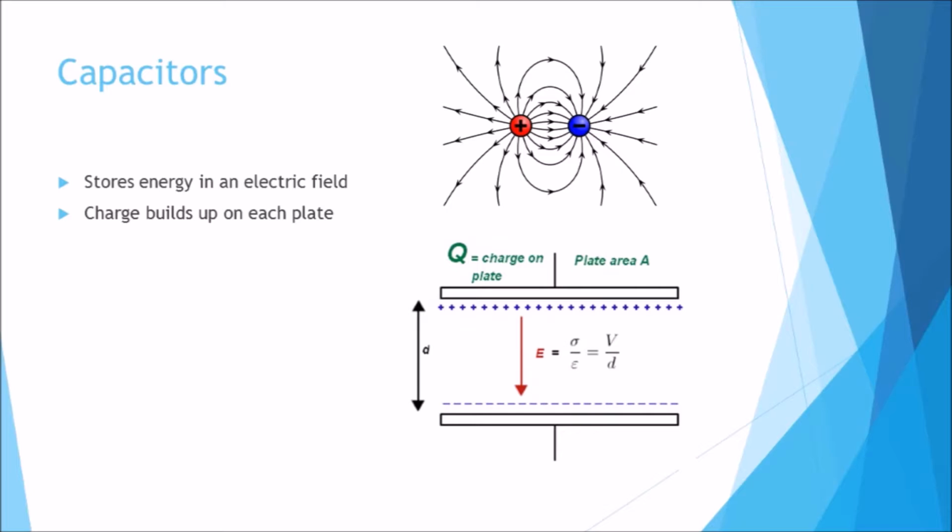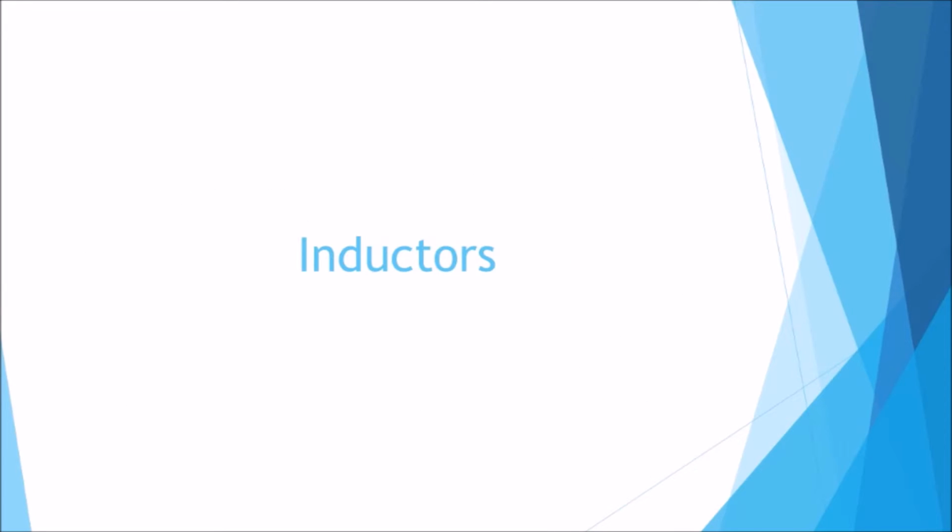For a capacitor, this built-up electric field resists the change of voltage across that element, creating a reactance. In AC circuits, as the voltage is constantly changing, this translates to a constant opposition to the voltage, creating what has the same effect as a resistor would in a DC circuit. The way that reactance in a capacitor can be calculated is by using the formula 1 over 2 pi FC, where C is capacitance in farads and F is the frequency of the source.